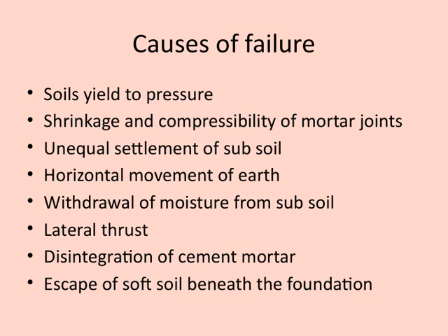Let's take a closer look at the causes of failure in foundations. One of the main issues is that soils tend to yield to pressure, meaning they can compress or shift under load, leading to instability. Shrinkage and compressibility of mortar joints are also significant. As the mortar shrinks or compresses over time, it can cause cracks and weakening of the structure.